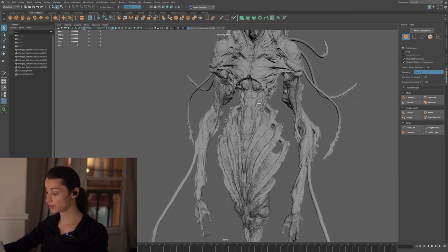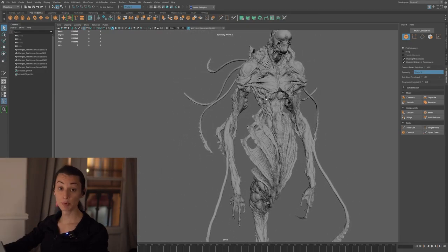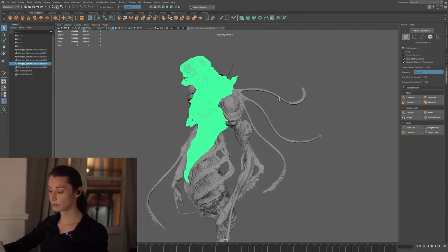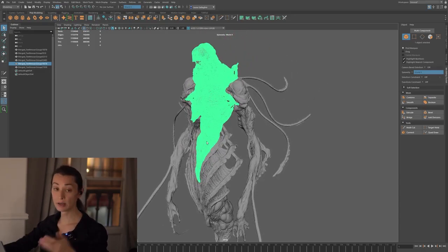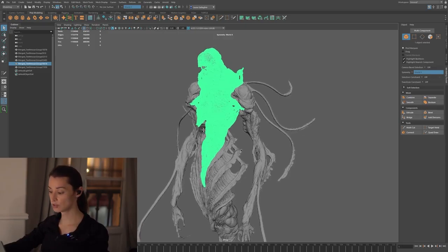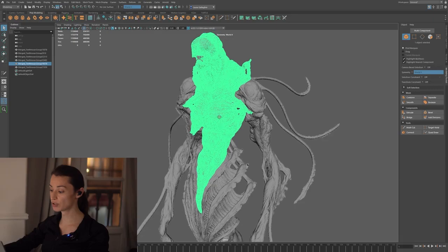Unfortunately, I probably should have taken the time to name it properly, but anyway, that is what we have here to work with. And as you can see, as I'm loading this within the scene, we have the object here that is displayed. Here we can actually rotate around the high poly. It looks like we have some nice performance, so that's great because we really need to have that. If upon import, the scene really slows down to a crawl, then it means that you have decimated your mesh to a result that is a little too dense. And you should probably go back to ZBrush and reduce the density of polygons that you have because it won't be workable to do retopology there.